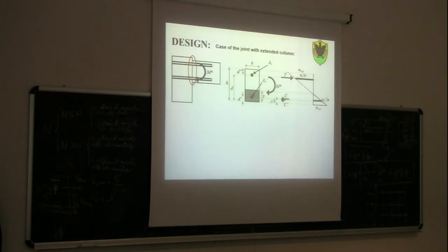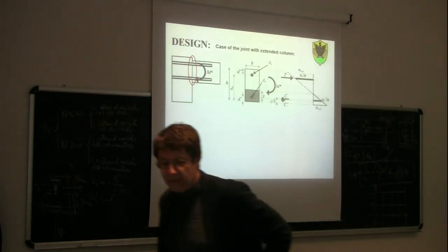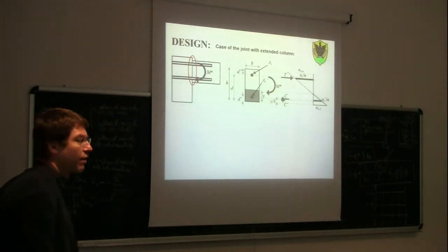So in other words, if you do a cross section here, we will find that if we have a hogging bending moment, which means a negative bending moment, you will have some compression at the interface between the column and the beam, in this shaded area. And then you will have detachment in the upper part. So basically you have no contact, so no tension on the white area of this beam cross section. This distribution of stresses is similar to the distribution of stresses that we have in a reinforced concrete beam at the cracked limit state.